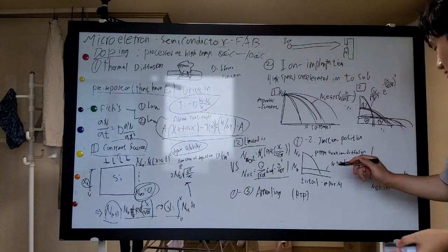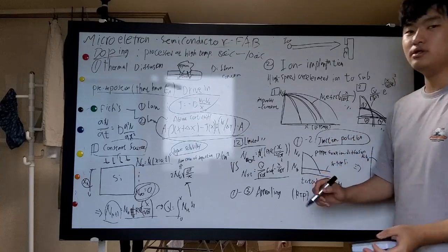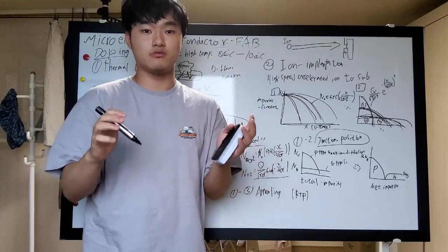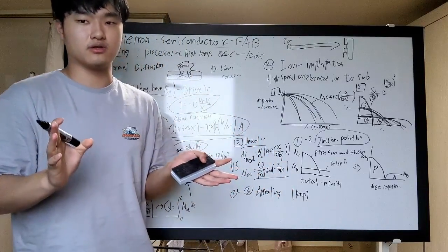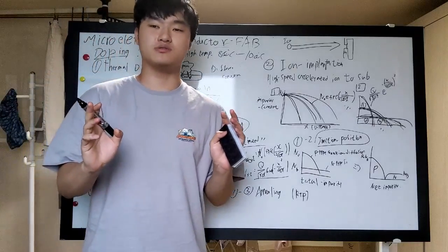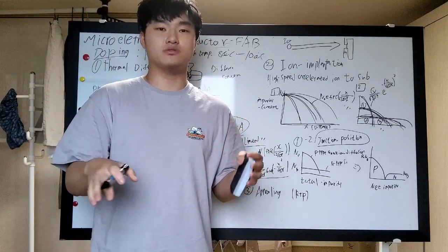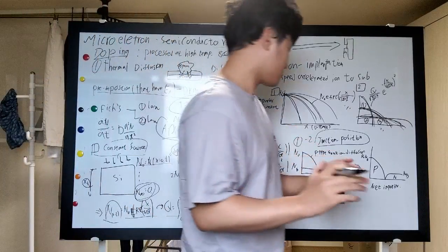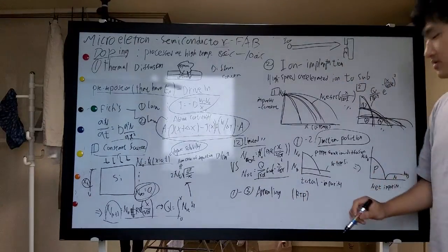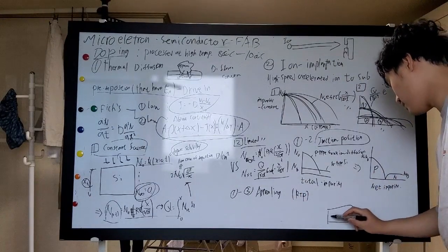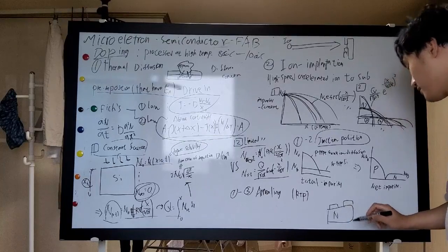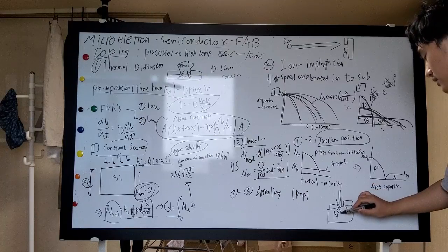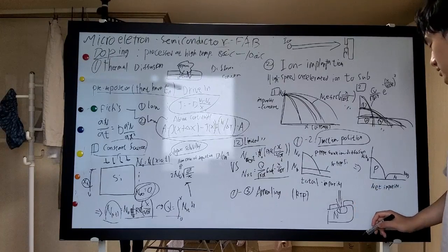Okay, secondly, the junction positions. See, we just started doping. If the silicon was not pure, if the silicon was somewhat lightly doped silicon with p-type or n-type, which means we have some species of carrier such as electrons or holes. So yes, a technical example: if we are doping on an n-type silicon, here's the mask, we will dope here, then if we dope with p-type, here we will change to p-type.